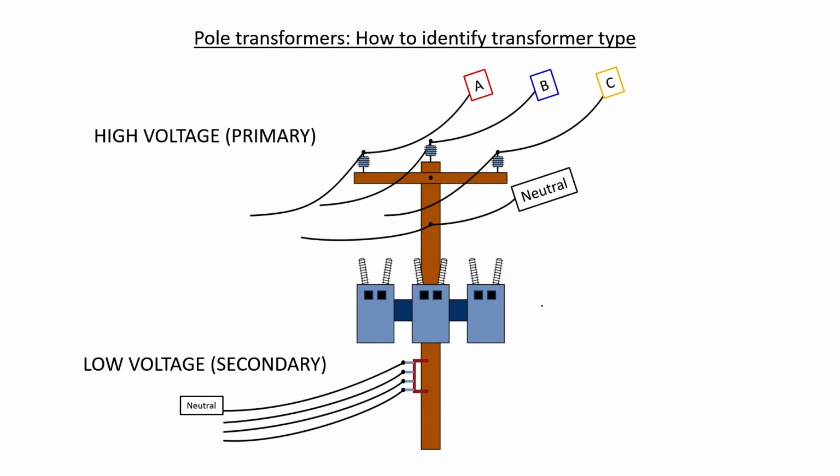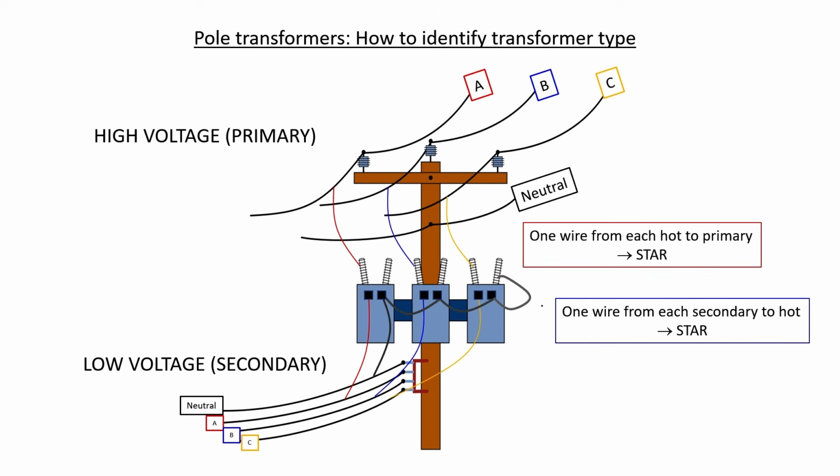You can tell that they're high voltage if they don't have black colored insulation, for example, surrounding the wires. If they're insulated, then they're typically at a lower voltage, and you might sometimes see 3 or 4 of these wires. If you see 4, usually neutral is at the top. The 3 lower wires then would correspond to the 3 different phases. Let's look at an example of how these 3 transformers might be wired up in a star-star configuration.